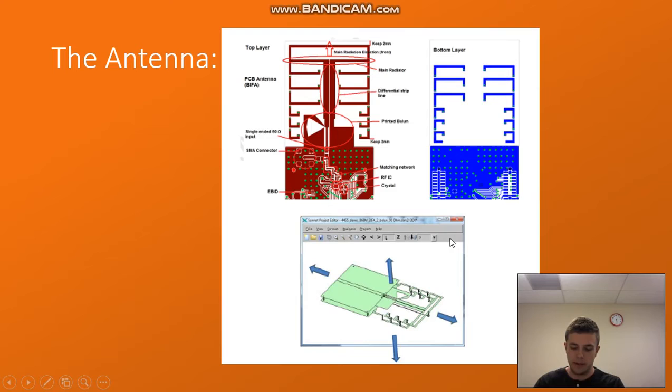And in the middle of the top and bottom circuits is the dielectric, which allows for the radiation to be emitted in a certain dipole region along these arrows, which is perpendicular to the dipole antenna itself. And from the length of the antenna, we want it to be in similar order to its wavelength, so that the physical length and the electrical length match up. Technically, that's why we wrap it from top and bottom, because it's about 1/2 meter in this diagram specifically.